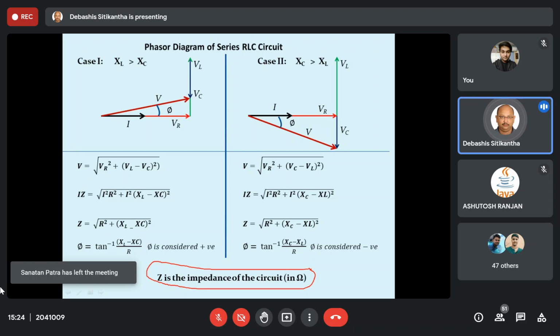In case of resistance, it is because of the friction between the current carrying charges that you get a resistance. In case of inductor, the XL is also an opposition, but how is it opposing? It is because of the induced EMF that it opposes the flow of current, because you know about Lenz's law. Similarly, in case of capacitor, why does it have an XC? Now XC is again an opposition to the flow of current. And what is the difference? The only difference is that XL is going to oppose the change in the current.